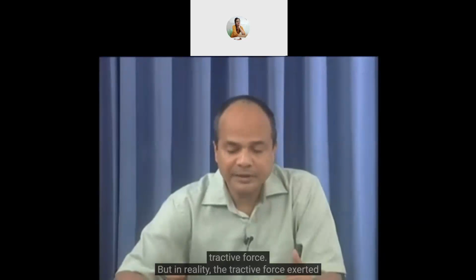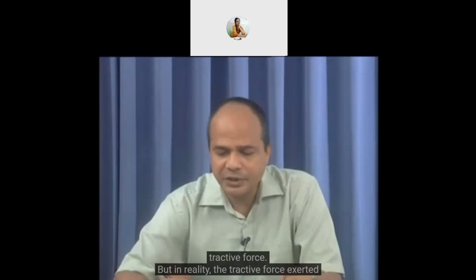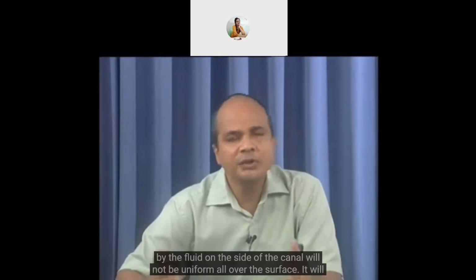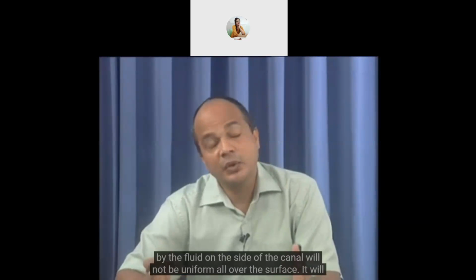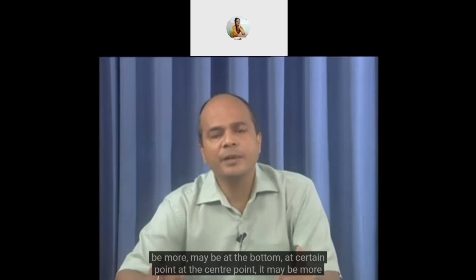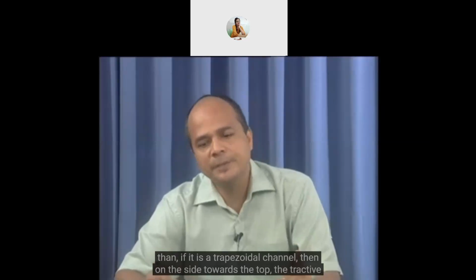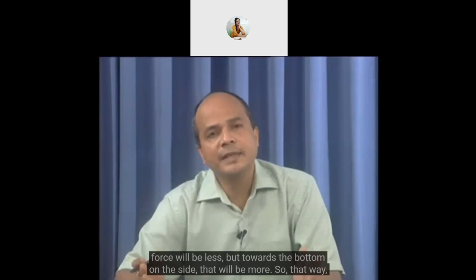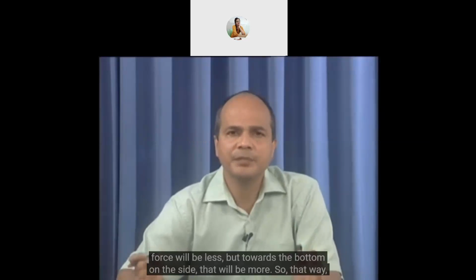But in reality, the tractive force exerted by the fluid on the side of the canal will not be uniform all over the surface. It may be more at the bottom, at the center point. Then if it is a trapezoidal channel, on the side towards the top the tractive force will be less, but towards the bottom on the side it will be more.